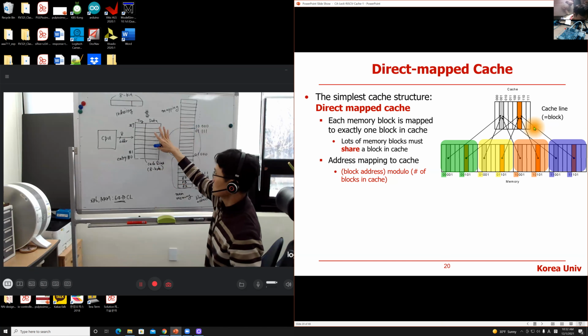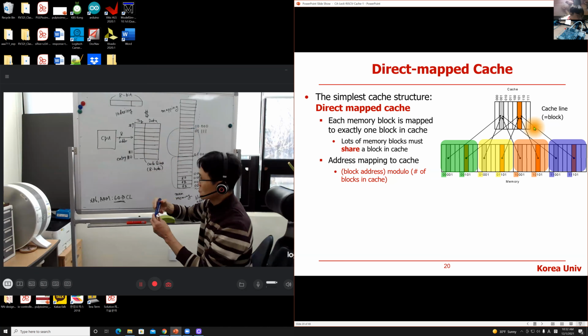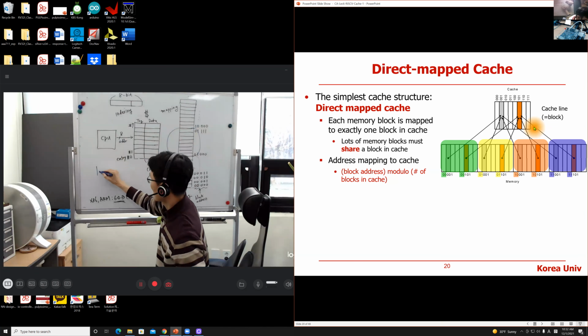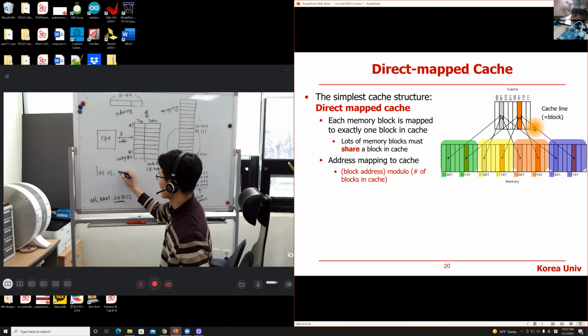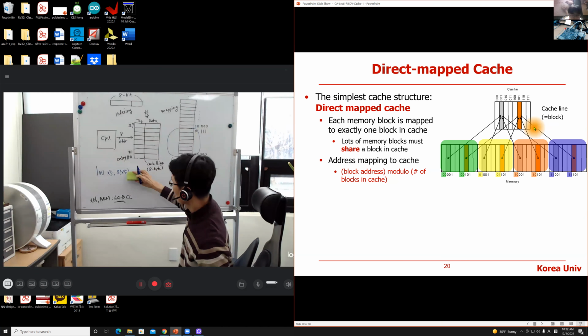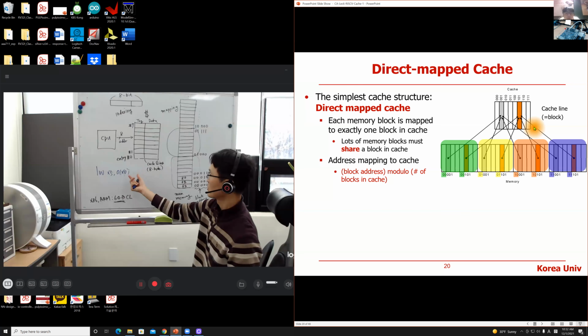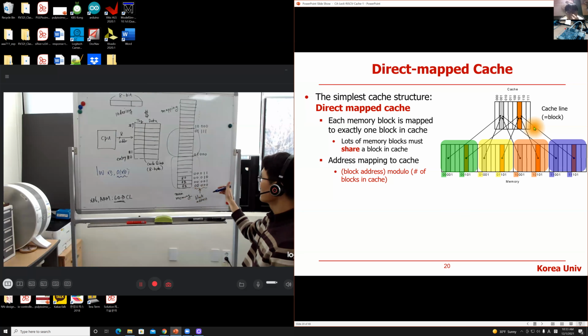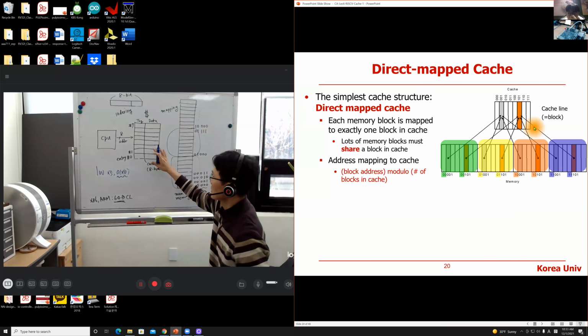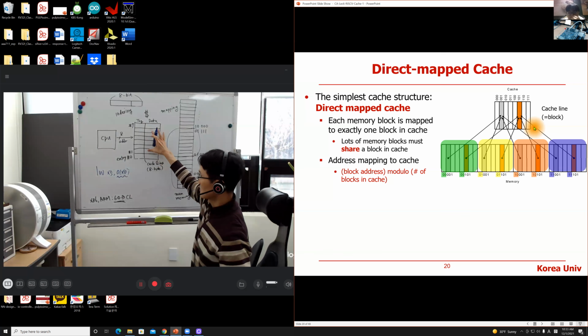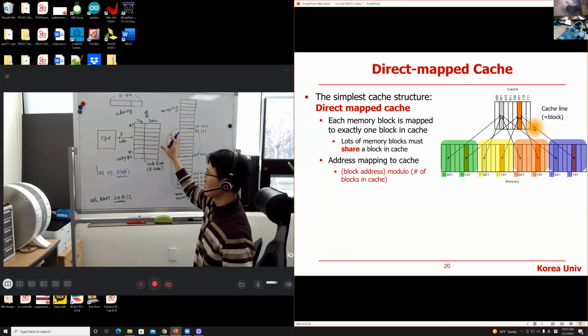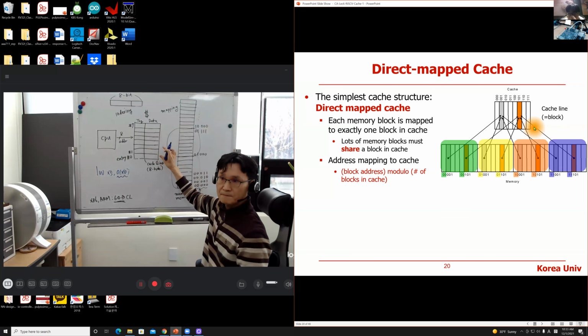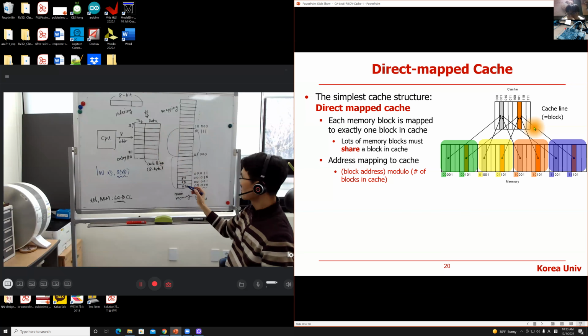If a cache miss happens, assuming the CPU is executing an LW instruction, for example, at location 0x0, that is better. You are executing that instruction, then you want to read the data from location 0, okay? And you search the cache first, but the cache does not have anything at the beginning, so we have a cache miss, right?